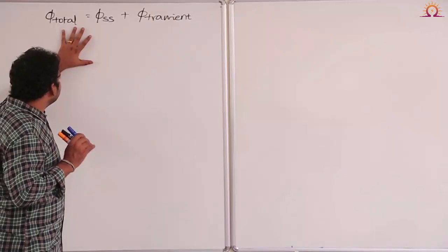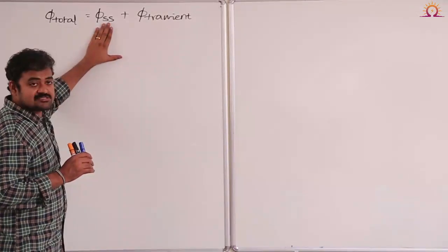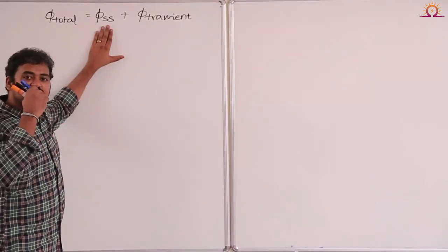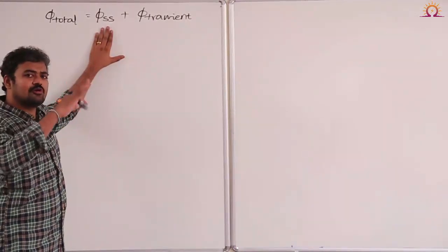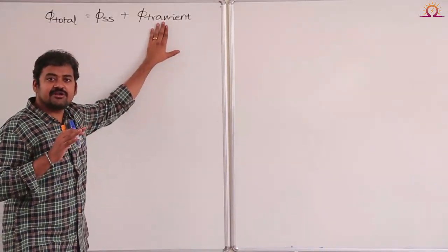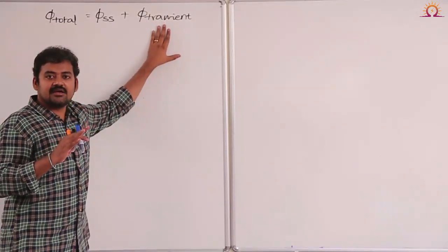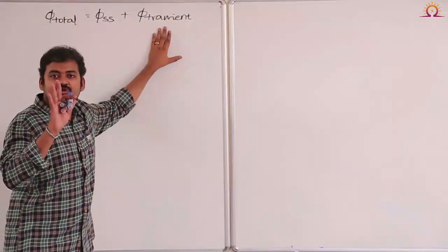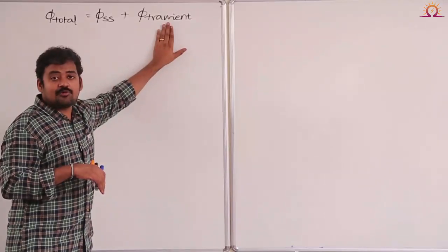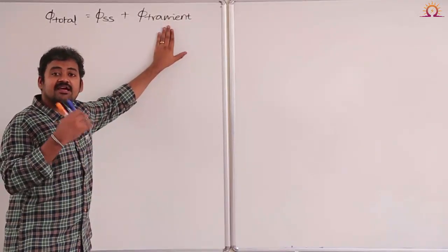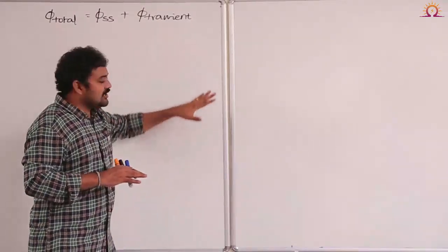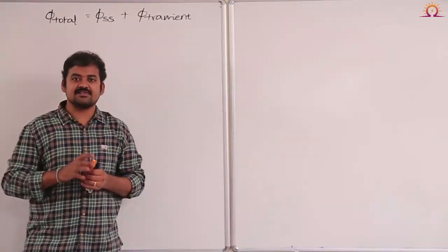Now, to understand the shape of the steady state flux, we have discussed already. Steady state flux will be purely sinusoidal and it is permanently available from no load to full load or any condition. Whereas transient flux is not sinusoidal, it is exponentially decaying and will be available for 5 time constants. Suppose if it is an ideal transformer, this transient component will be purely DC component and available permanently again. Am I right or not? Okay. Now, let me try to discuss two important cases here.